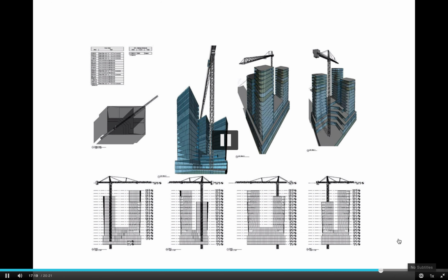And then depending on your permits with the DOT through OCMC here in New York, or whatever agency might be monitoring the sidewalk and roadway closures, you may not have a closure. So you might have to do a moving pick where a flatbed truck that has 5 or 10 members on top of it will have to pull up. The crane will access the member. It'll be safely picked and pulled away. And then the truck will have to pull away again also, so that you can reopen that roadway.